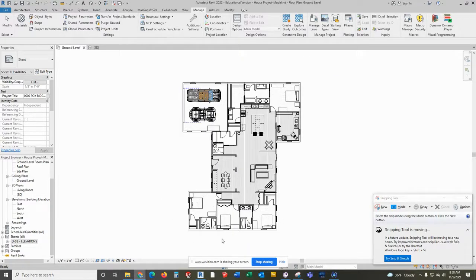The main thing that we need to do is we need to create clean views of every exterior wall. So what that means is I want to be able to see the entire wall unobstructed, no trees in the way from my site plan, no anything else in the way. Literally walls, doors, windows, parts of the house, all right? We're even going to hide the roof and the ceiling so that all we have is the wall, okay? And the one thing we want to do is we want to keep track, all right?